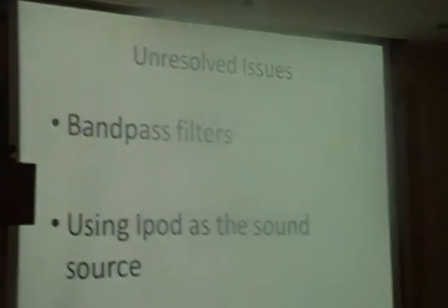Issues. The first of them being the bandpass filters. I was able to design the bandpass filters, and they worked fine with the signal generator, but when we used the sound signal as the input, somehow they weren't filtering out the sound at the cutoff frequency. And so we settled for using only 2 speakers to get the distance.